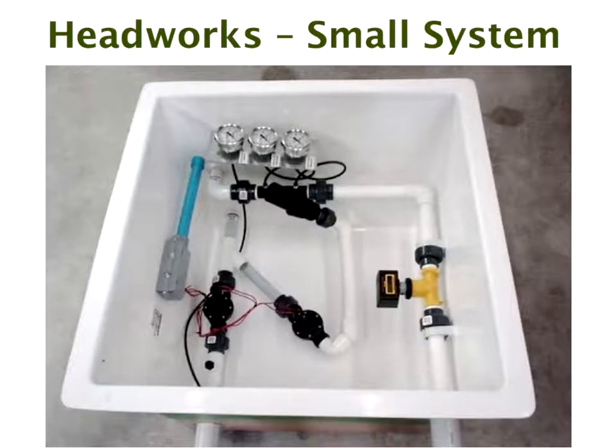Yesterday, I got a little confused on this slide, so just to clarify what I said about these 3 gauges up here. Why are there 3 gauges? Well, let's say this one and this one are across the filter, so they give you the pressure drop across the filter. And the one on the outlet of the filter is giving you the pressure out to the field, which is now going through a flow meter.